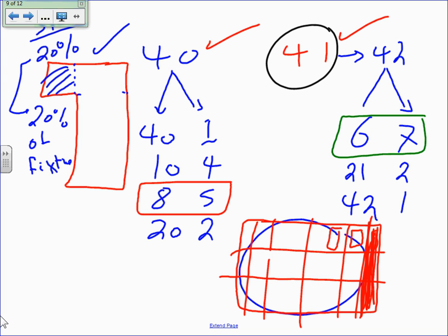And when you're done, if you end up with a fixture that's located right in here, where this is a wall, move it. Bring your fixture here. It will give you a good starting point for any shape. If your shape is not a rectangle or a square, which is a special case of rectangle, then enclose it with a rectangle, to the best of your ability, and do the calculation based on the rectangle, columns and rows, and then lay them out. Then you might have to shift certain things to fit the shape of your room.